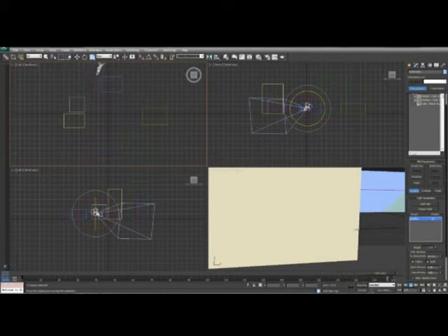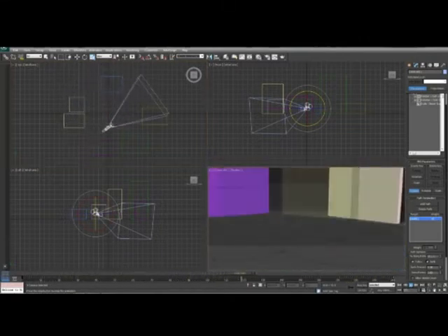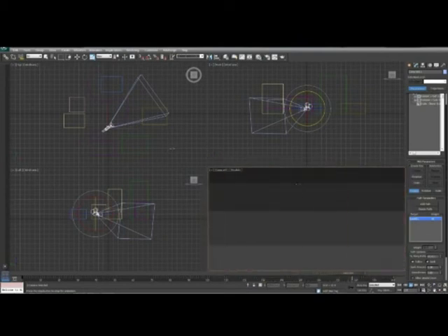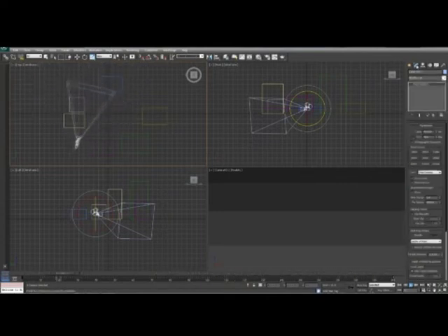The next thing we're going to do is adjust the camera itself. If we notice down here, we get real close to the buildings. It's hard to see what's going on, even though we've got the camera moving smoothly up here. So in order to do that, we're going to come up to the Modify tab, click on our free camera, and we're going to select a stock lens. We have everywhere from 15 millimeter all the way up to 200, and we can actually do a custom lens if we want right here.